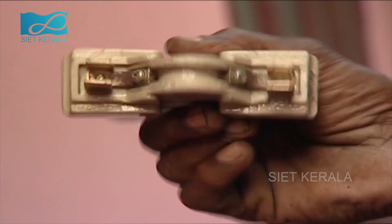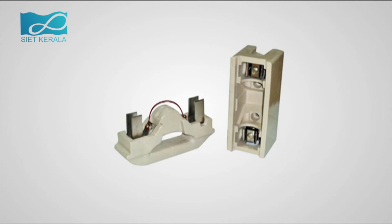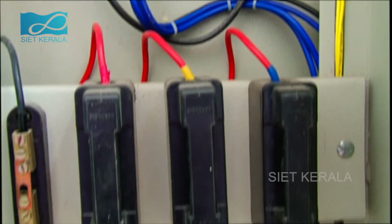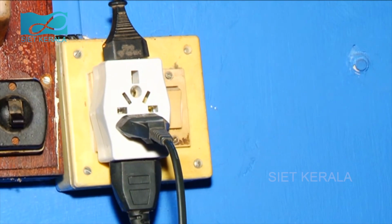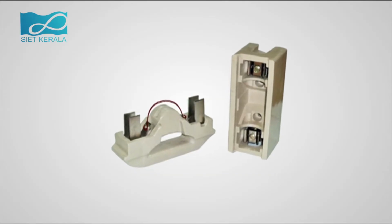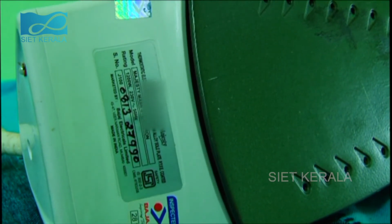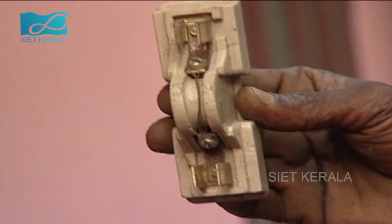Safety fuse is a device that protects us from such dangers. The fuse wire, which is the main part of the safety fuse, has a low melting point. Whenever there is current through the fuse wire, it gets heated. But this heat is radiated to the surroundings. When there is a short circuit or overloading, the current increases very much. The fuse wire gets overheated. As a result, the fuse wire melts and breaks the circuit. The current in the circuit depends on the amperage of the devices. Hence, we should take proper care to see that fuse wire of appropriate amperage is being used.